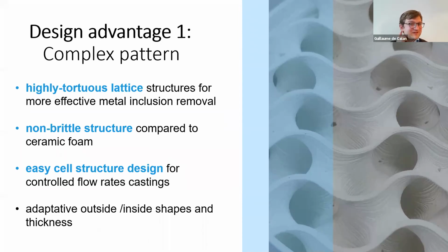You mentioned compatibility with standard FDM printers. Is there a list of printers and furnaces' sintering profiles which has been tested and certified for your materials? So for the furnace and sintering profiles, that's very simple. We give sintering profiles. So if your furnace can follow it, it should be compatible. I should add that if you want to make metal parts, you need it to be compatible with neutral gas. So you need to have the possibility to put it in pure argon or hydrogenated argon.